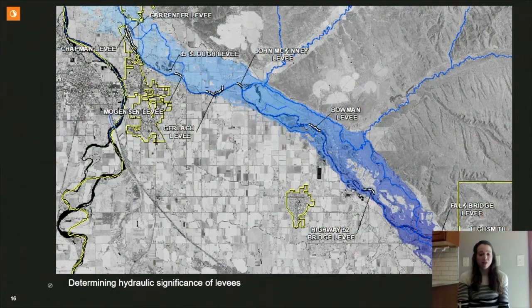The final scenario is when the height of the levee is low compared to the water surface elevation over the crest of the levee for the majority of the length of the levee. This also did not apply to any of the levee systems modeled in this reach. For this reach, the differences in inundation area between the with levee and natural valley results were negligible, but comparing the water surface elevation, these levees do provide some hazard reduction to the area landward, even though most levees do not tie into high ground, making every levee system in this reach hydraulically significant.